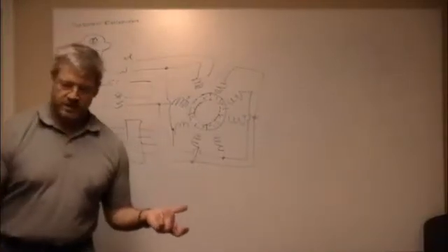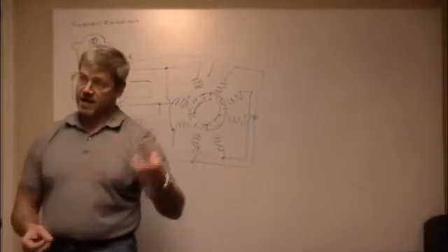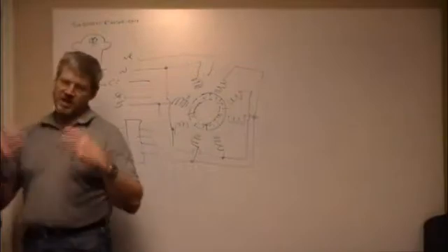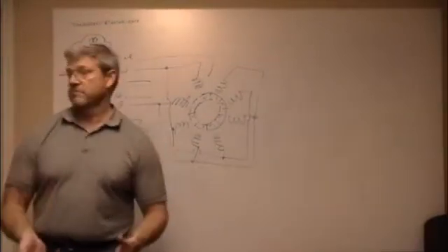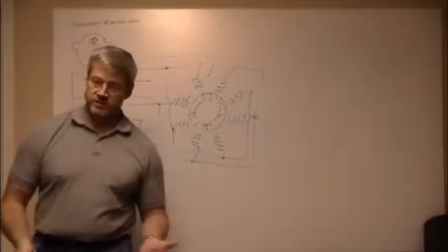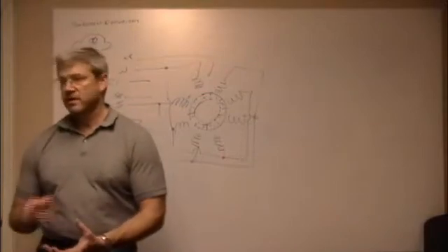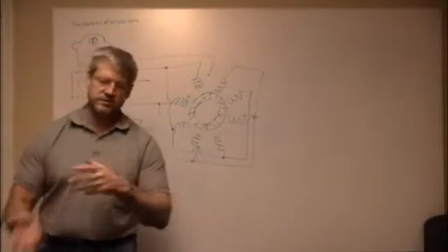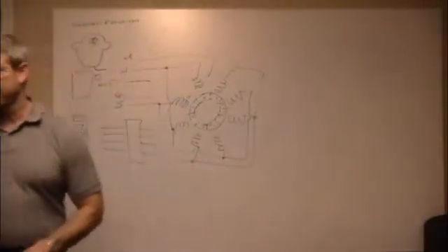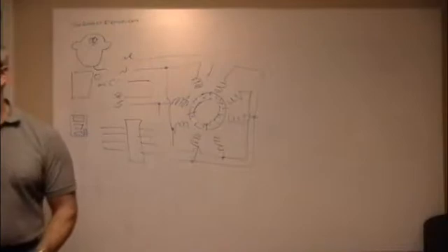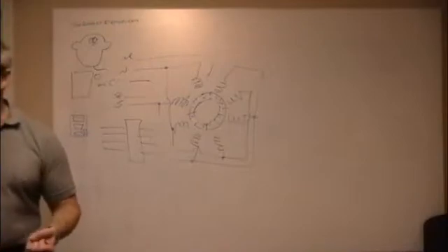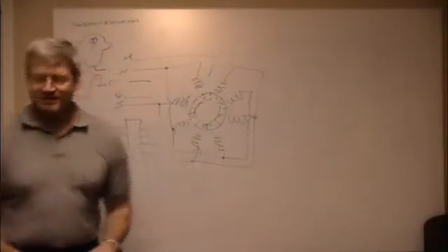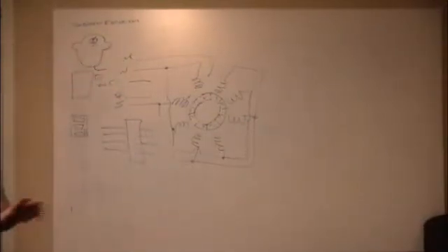Well, if I want to do a real high power servo, then I have to build my own complete control loop and all the power electronics for it, and that's going to be expensive. Or I can do a single stepper and a single stepper controller, and it'll handle most of that for me, so that's cheaper. There's all sorts of trade-offs. Yeah. Just like any engineering activity, right? You're not looking for the best solution. You're looking for the one that meets your price and the one that meets your requirements. Right. And there's 50 ways to get there from here. So that's the big difference.